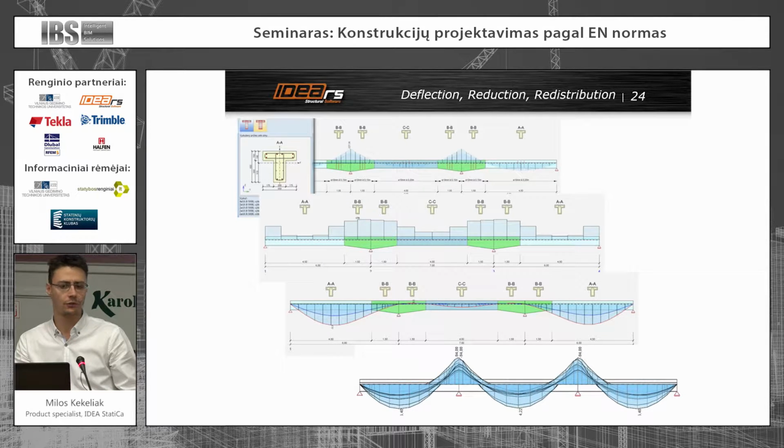So in the second picture from the top, there can be seen the variation of stiffness due to the cracks. As well, we can calculate the long-term and short-term deflections that are presented in the third picture, and as well there is the functionality of the software that the structural engineer can use to enable the reduction and redistribution of internal forces. So the design can be more economic.